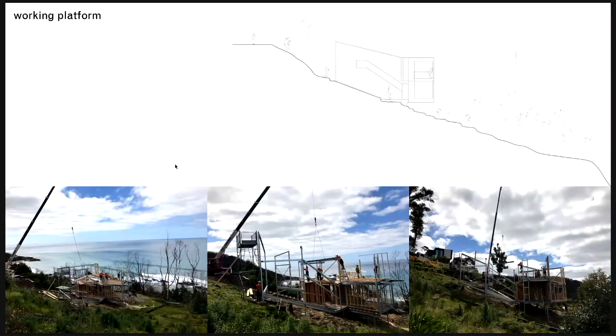We also focused very carefully on how this construction was going to take place, because there were these very difficult challenges of access. So we settled on the use of steel to minimise excavation to the site, with the problems of landslip and so on, that was founded into rock. And those early shop drawings meant that we could set the geometry very early on in the process, which the builder could work off, and this became effectively a working platform for them to build. So it's a really effective way of dealing with this problem of site access.